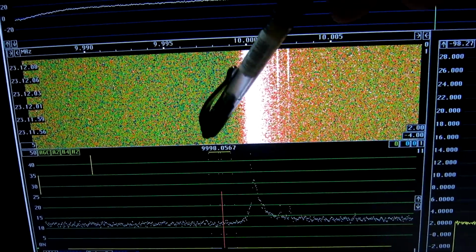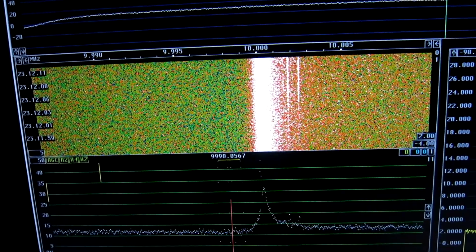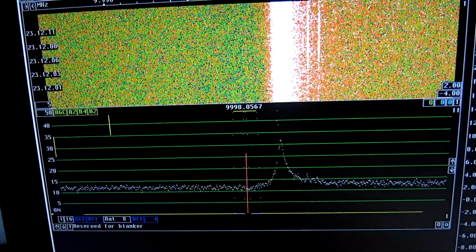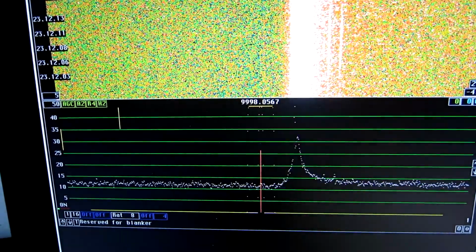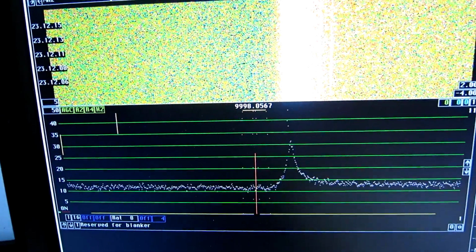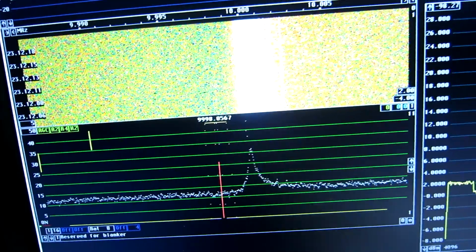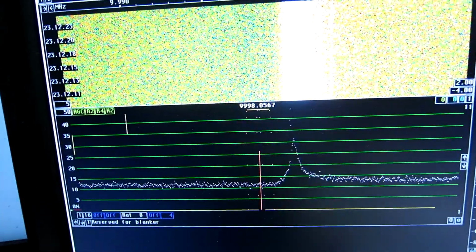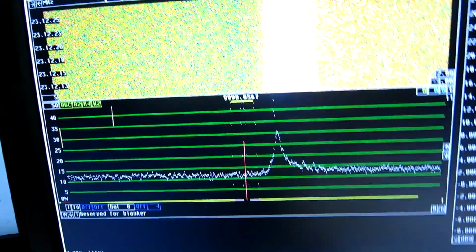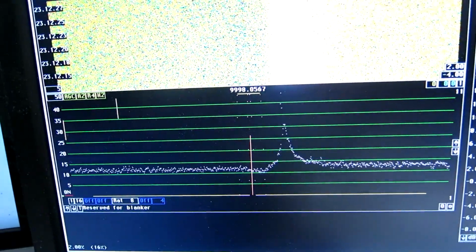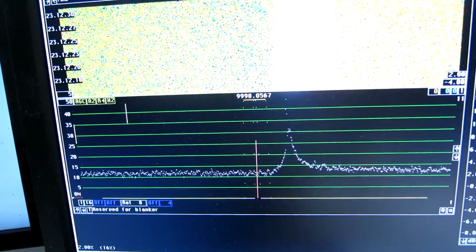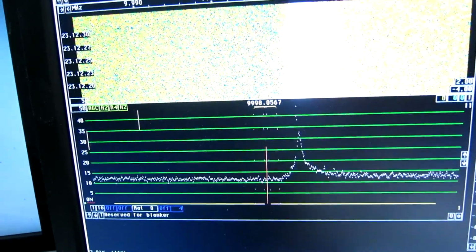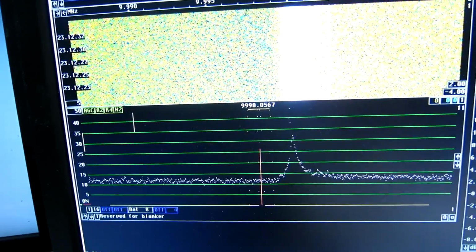Here is the series resonance. And I'm looking for the noise floor at the frequency of the series resonance. I can bring down the noise far away by putting more crystals in parallel to get a bigger capacitance. That will not increase the load on the crystals because that is determined by the voltage.